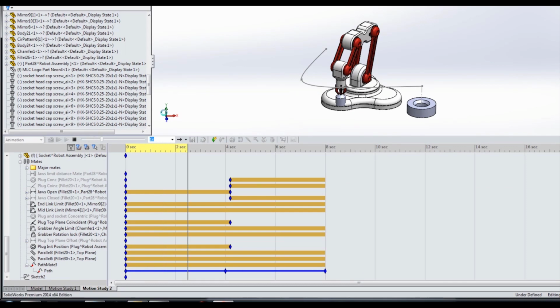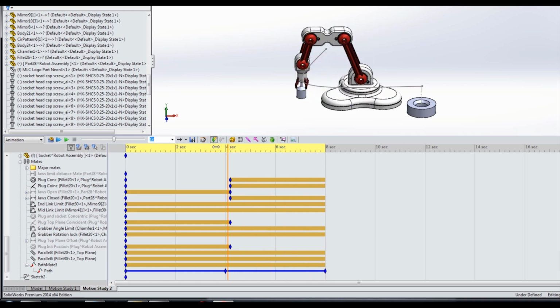We're just going to let this run, and then we're going to make sure that that point stayed where it needed. And this is why it's so important that when you start creating these paths and any of these relations, you don't simply snap to geometry, because that can get you in a lot of trouble. So here's a good example.